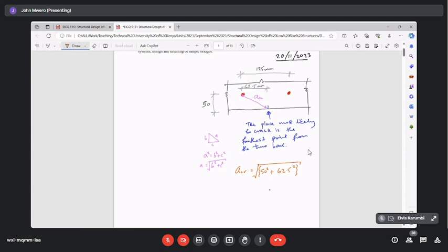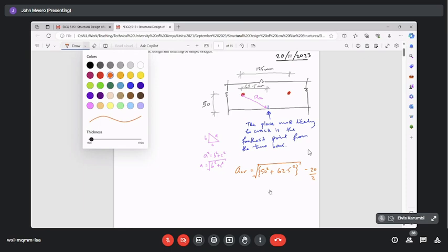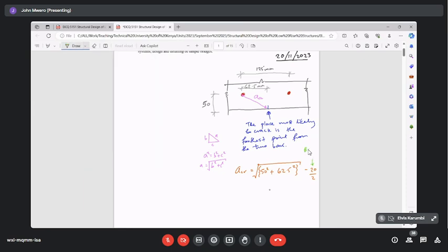Then, because the reinforcement bar we are using is 20 millimeters, and we have measured ACR from the center of the bar, the surface of the bar, which is what we are interested in, will be 10 millimeters closer to the point where it's likely to crack. So that's why we subtract. Subtract 20 over 2, the bar diameter over 2, so that you can remember. So with that equation, we can find SCR is 70 millimeters.